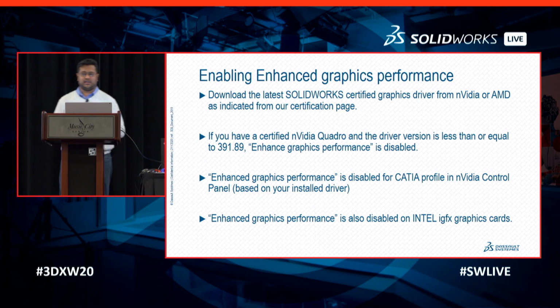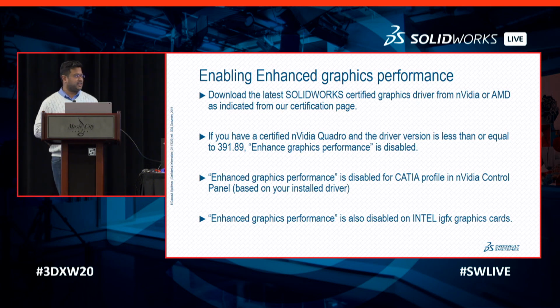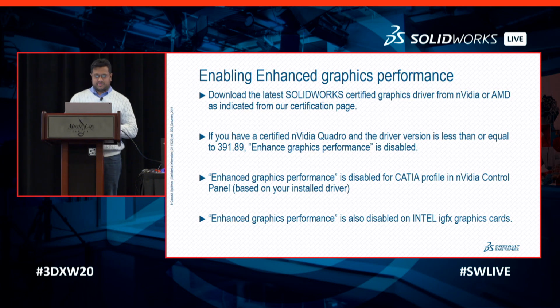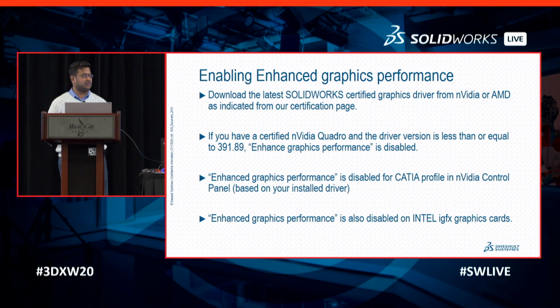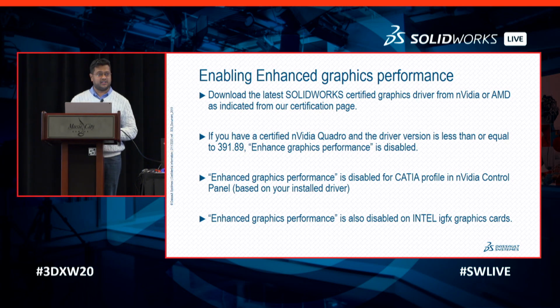So you must be very careful that you get your certified drivers. It's also disabled for CATIA profile in NVIDIA control panel. How many of you know about NVIDIA control panel and how to set profile settings and stuff like that? Okay, quite a bit of you. All right. So that's something to take into consideration. And it's also the enhanced pipeline, the graphics performance is also disabled on Intel integrated graphics. We always go with the discrete graphics card.